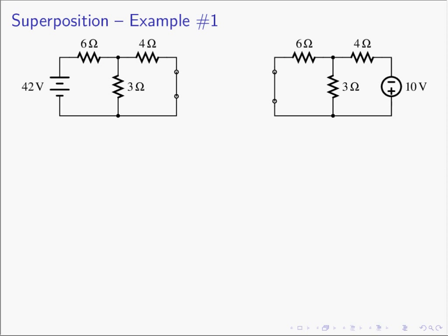So if we redraw the circuit, you see we have this. And again, keep in mind what we're after. Ultimately, we're looking for this current right there. That's what we want. This is a different circuit, so we'll call this I3A. This is the current in the 3 ohm resistor, and we'll put an A because this is the A problem, the sub-problem A. How do we find I3A? Well, let's back up and find this current right there, and we'll call that simply I42A.